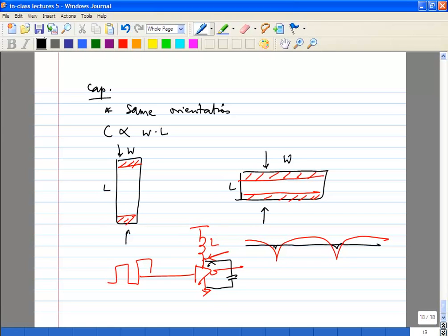Now, you're basically relying on the fact that the capacitance is low impedance for that pulse of current, right? If you have some series resistance with that, you can be pretty sure that you're going to kill your decoupling. If you do a layout like this, it's a perfectly good way of killing your decoupling. Similarly, you can show the same thing for your MOS cap.